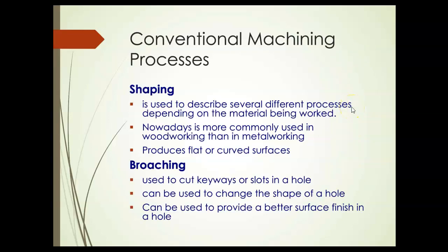Shaping and broaching are kind of the two similar things. Shaping and shapers have kind of fallen out, but basically we're more or less shaving material away with either shaping or broaching. You still have a lot of shapers used in woodworking, so they produce flat or possibly curved surfaces as we cut into that material.